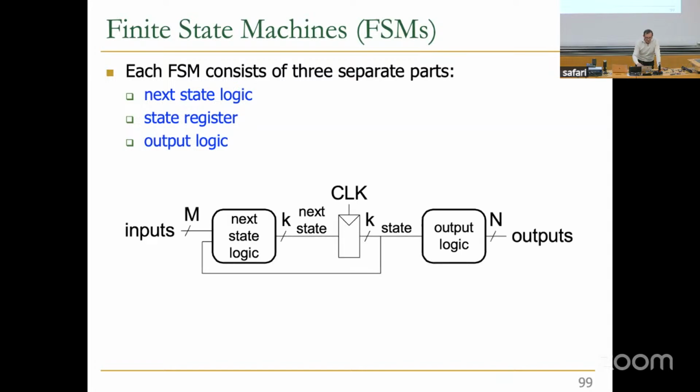Okay, it looks kind of like this, basically. This is our state register. We're going to add a clock to it soon. So far, remember, we haven't added the D-latch. D-latch is not going to work for this purpose, so we're going to introduce something else. This is our state. Based on the state, we can generate some output. That's a particular type of machine. Don't worry about that. But based on the inputs and the current states, we determine the next state. Actually, output can be determined based on the state as well as the inputs. This doesn't depict the general case.